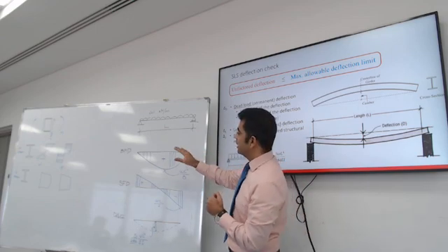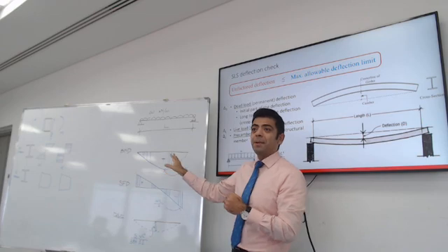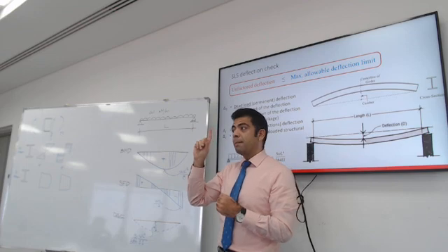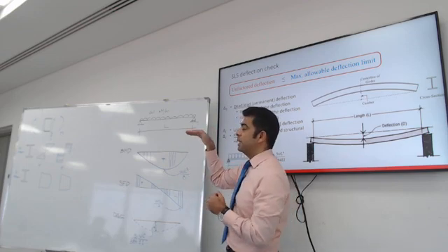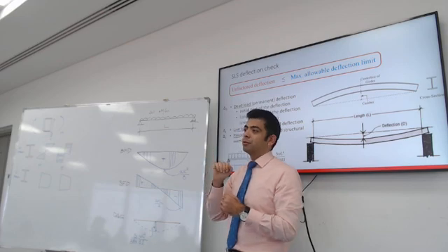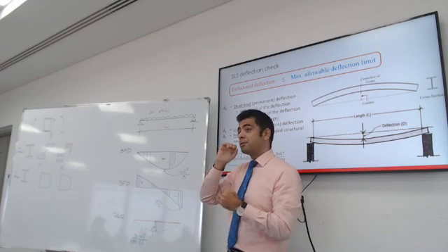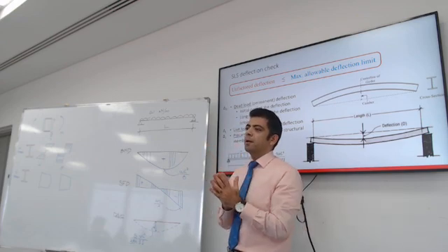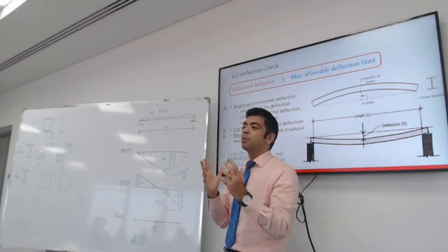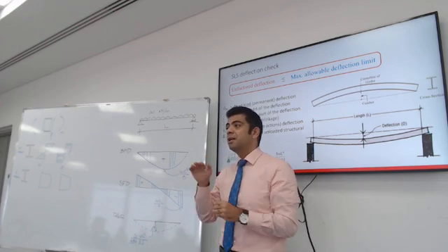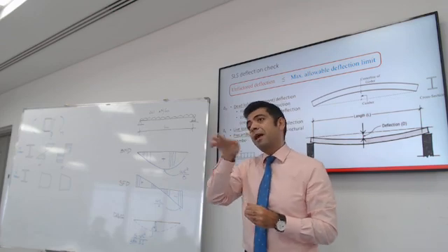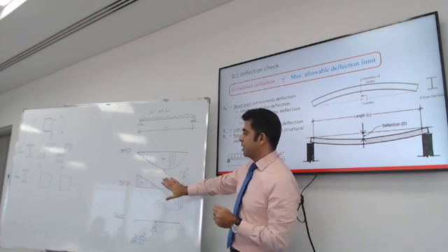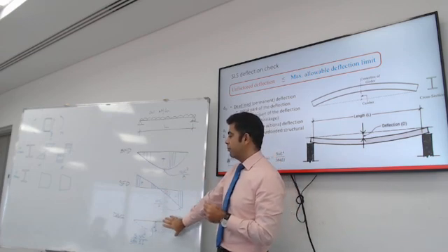Last week, we dealt with the flexure design, or bending design. And in order to do that, there is one major question you need to ask yourself. Is this beam laterally restrained or unrestrained? If it's laterally restrained, it's pretty straightforward. If it's unrestrained, it takes a little bit more time to figure out the capacity. And in essence, you need to reduce the capacity to account for the possibility of lateral torsion buckling. We covered this part. Today, we're going to talk about shear design and how to check for deflection.